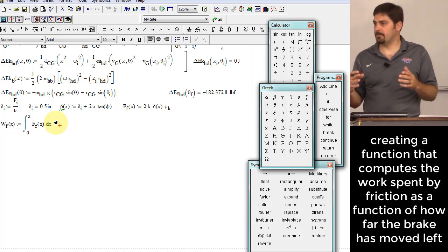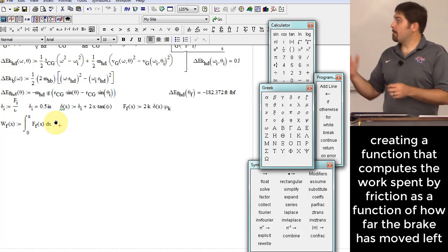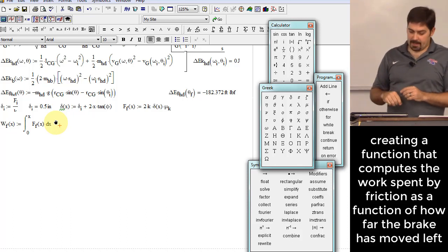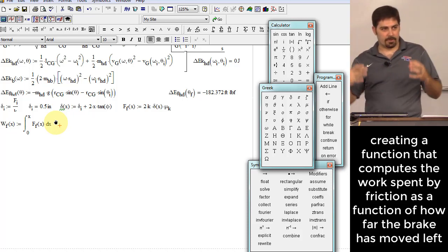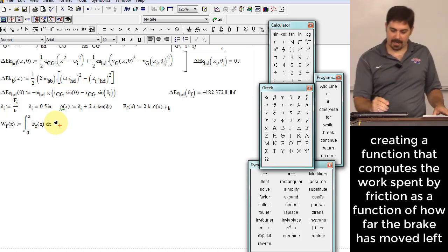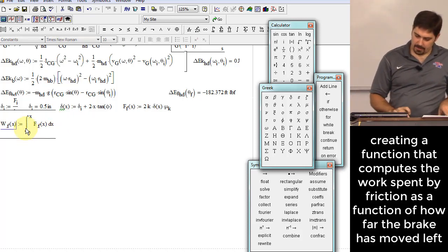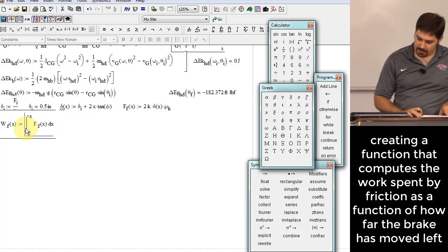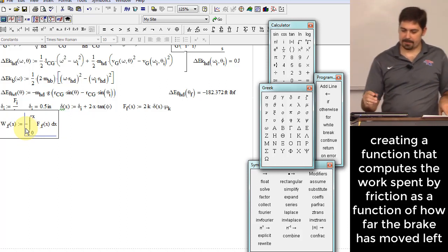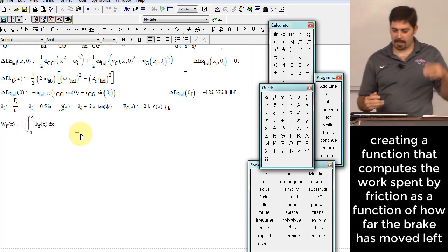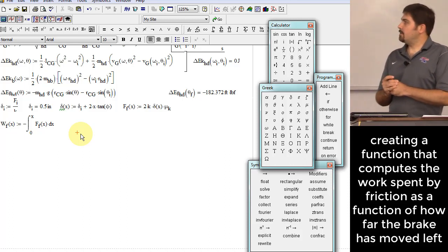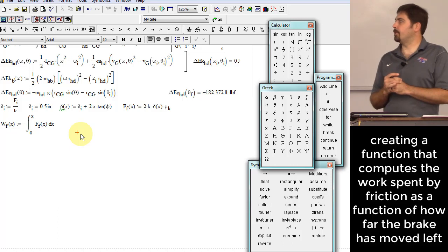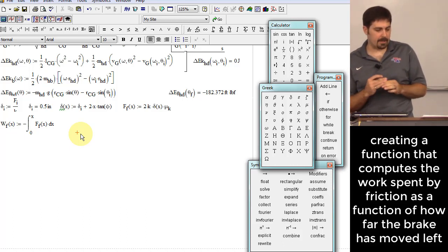You can decide to put a negative sign either right here and indicate this as a negative energy value, or you can do it in your ultimate energy balance that you're going to do later. I actually prefer to do it right here and say this is going to be a negative amount of energy, as in it is leaving the system. All right, so there's my work term. What else do I have? Is there anything else that's storing energy?